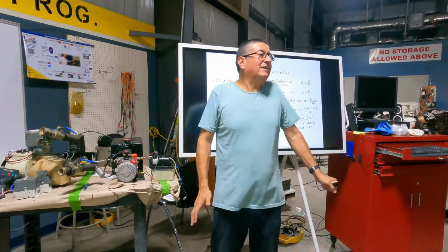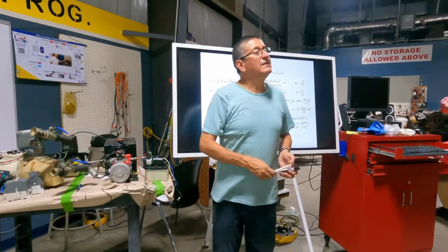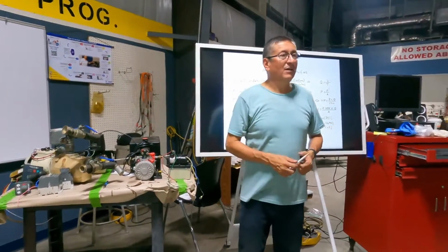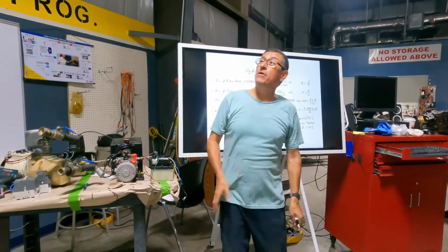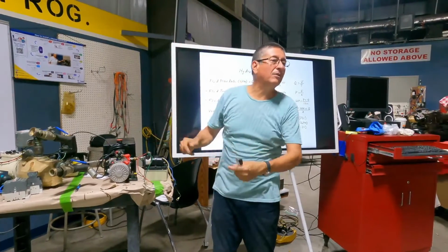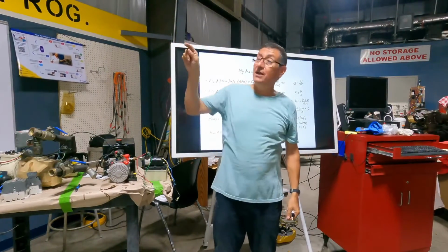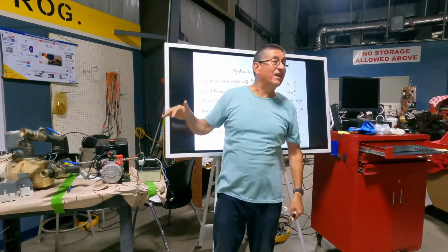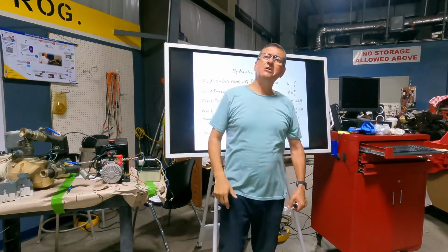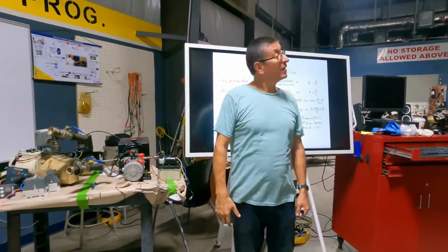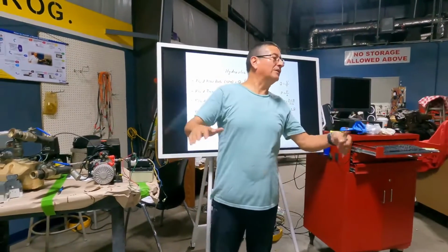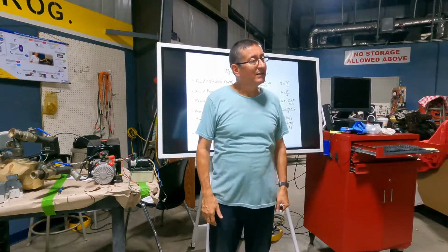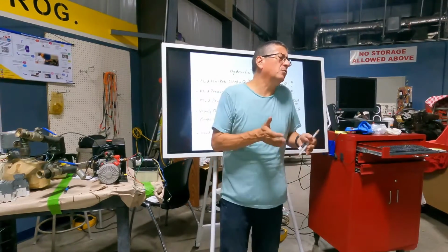It's exactly the same as when you size the inverter. You remember? I need an inverter to provide power for the entire AC panel. Let me check how much is the consumption in this breaker, this breaker, this breaker. You added all of them. And after that you said, I need 10 kilowatts. Okay, 10 kilowatts, or 5 kilowatts or whatever. Didn't you put an extra percentage on? Yes, normally you added 20%.